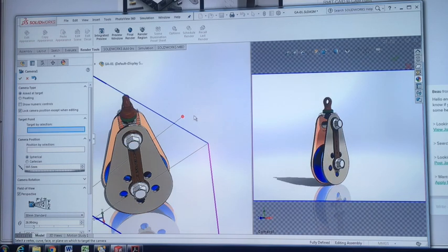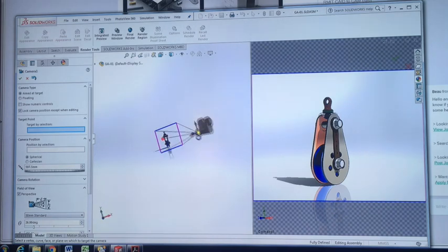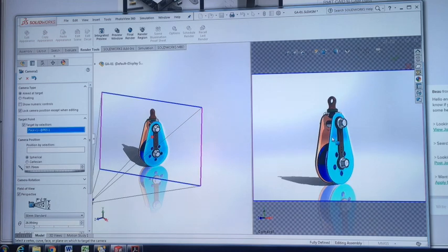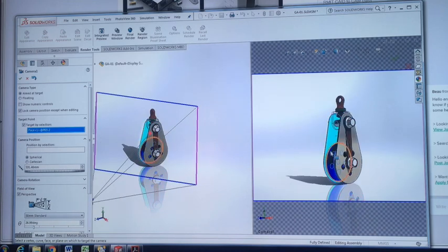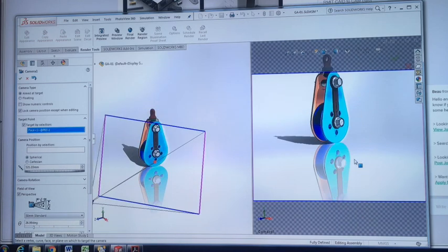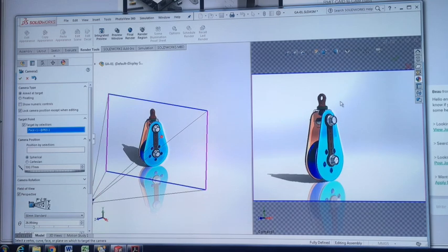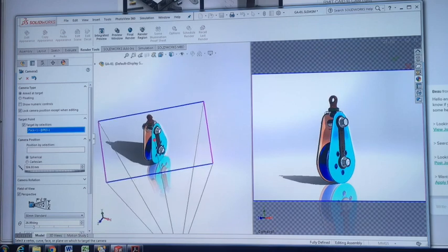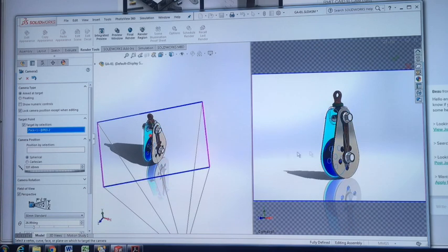On the left, if you click in that left viewport, you can zoom out and you can see where that camera is and where the camera is targeting. Okay, so at the moment it's not targeting anything in particular. What you can do in your viewport, click on a part and the camera will target that selection. So it'll basically center the camera around whatever you select. You can do that in either of the views.